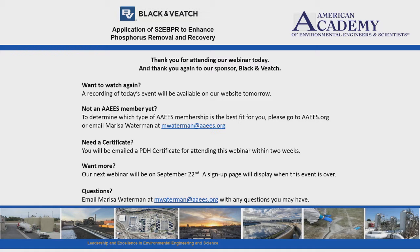Yes, I could just add that in one of the slides I showed, a plant in North Carolina, we're doing the BioP only on half of the plant. On the other half, chemical addition is added, but they've got this A/O process. In summer it seems to be working okay, and they reduce the chemicals to near zero. So it is possible, but it's a balance, as Leon said. I remember one plant where we tried to augment the BioP by adding chemicals, and we ended up just adding chemicals.